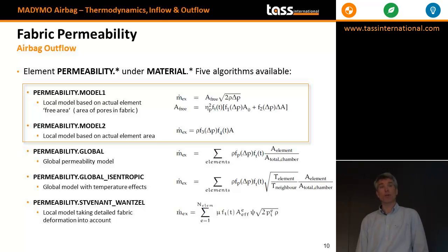However, if you're going to apply uniform pressure, the pressure will be everywhere the same inside the airbag model. And for that reason you will get direct outflow, although physically it might not be the case at that moment. Defining a time step function, you can control that more. So for example, for the first 10 milliseconds there is no outflow possible, because you put the time function to 0, and gradually you can let it grow to 1.